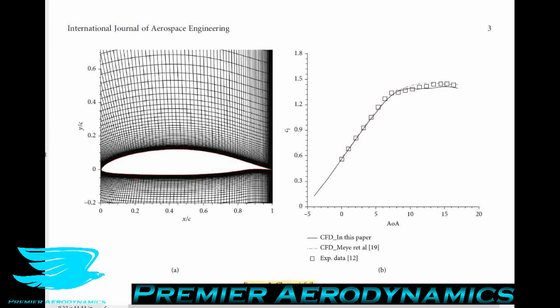So that's really good. So we have quite a run-of-the-mill lift coefficient, but we have a very low drag coefficient, and this is somewhat expected considering this is quite a thick airfoil, so we do get the flow accelerating quite a lot over the top, and it will come down quite nicely with the pressure drag being quite low, at low angles of attack at least. Now, because it is cambered, it means that we do have lift being produced at non-zero degree angles of attack. So what about the RANS of the CFD?